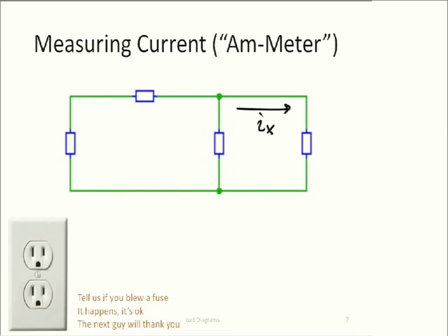So there, if we want to measure current, that current better flows through our ammeter, right? It's got to really go through the ammeter, otherwise how could the ammeter know what the current is? And how do we make the current that is flowing in that wire go through the ammeter? Well, we first have to break the wire, right? And then we have to connect it.